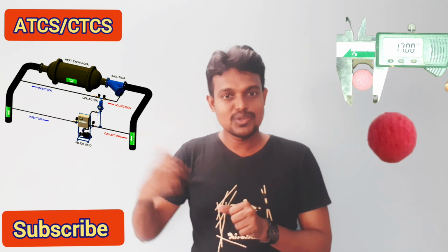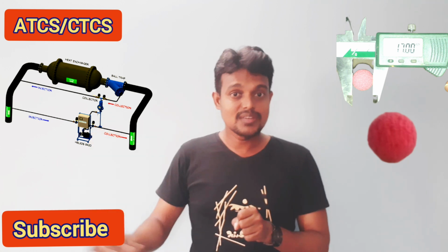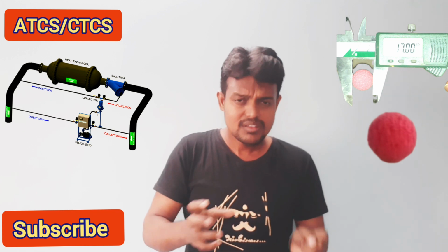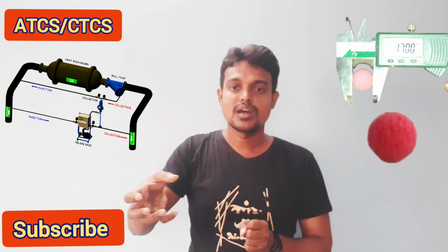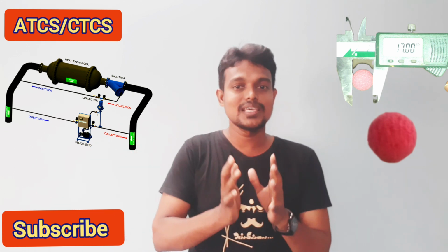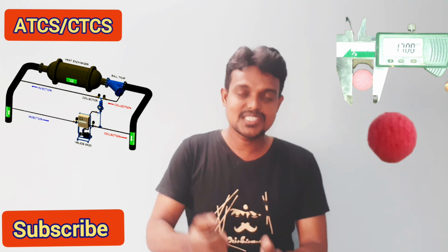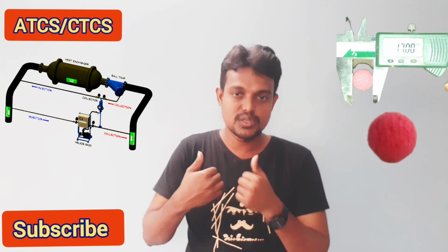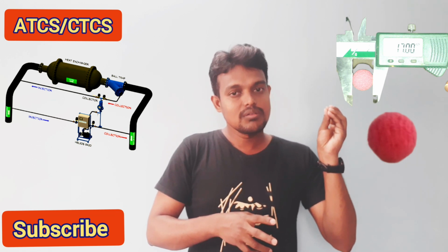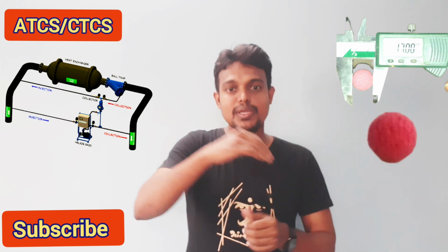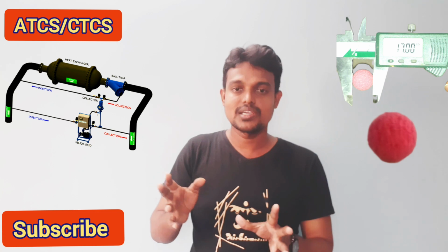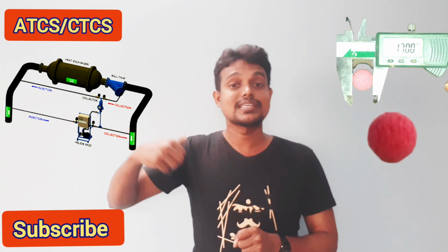And again, you have the external pumping system. That pumping system will suck the ball from the strainer, and it will come back into your ball collector. This is the collection cycle and injection cycle. The injection cycle means you will be injecting the balls into the condenser coil, and the collection cycle means the sponge ball in the ball trap is coming into the collector. So both the injection cycle and the collection cycle are happening because of the external pumping system.